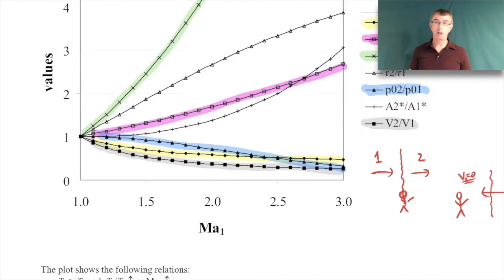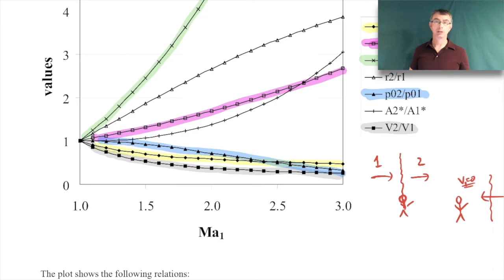All right, so it's worthwhile for you to know what direction these properties head in across a shock wave. So it's worth knowing that the temperature, density, pressure, they all increase across the shock wave. The Mach number decreases, the stagnation pressure decreases, the sonic area ratio increases across the shock wave. So it's worth remembering those trends. They just help you double check to make sure everything makes sense.